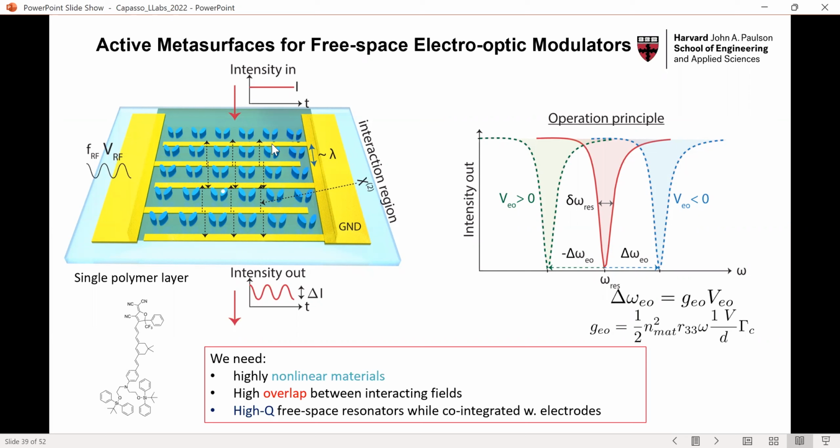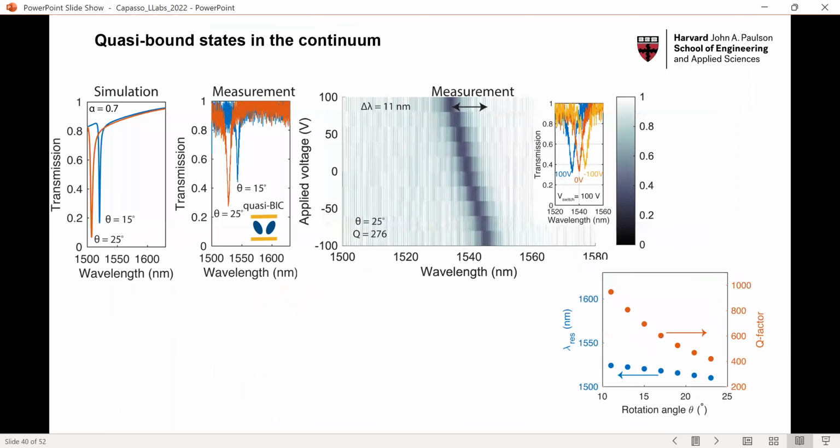Then after you are done with this, you can apply the actual modulation, and the modulation, essentially via the electro-optic coefficient, because you change the refractive index of the material in which these resonators are embedded, you can shift the actual resonance. And it works pretty well. I really think this is very promising for application, because organic materials and electro-optic polymers in particular are past the stage of just basic research. They're essentially waiting for new types of application, and we decided to go after that with modulators.